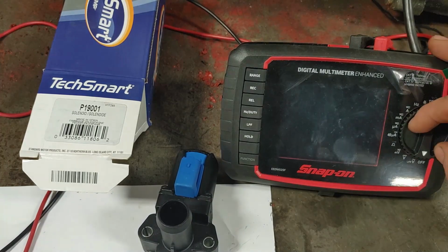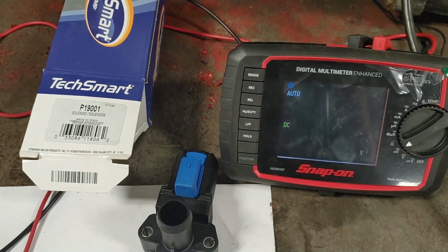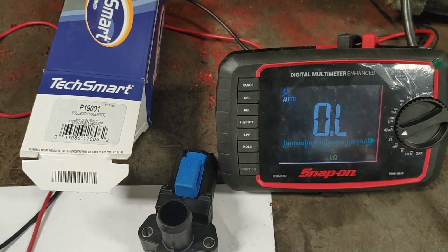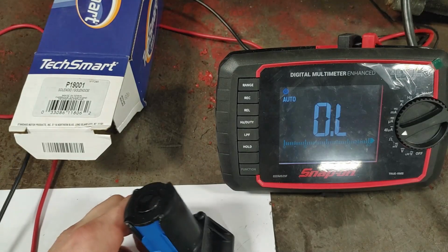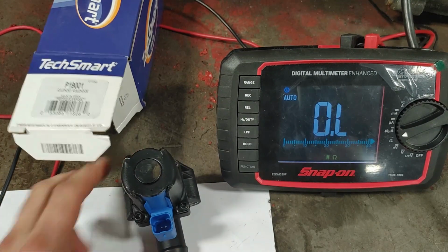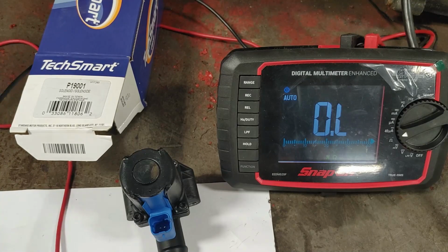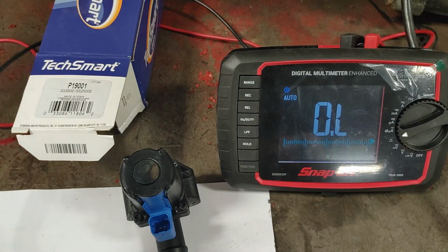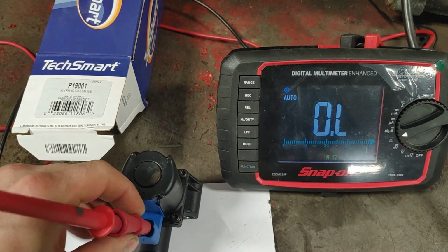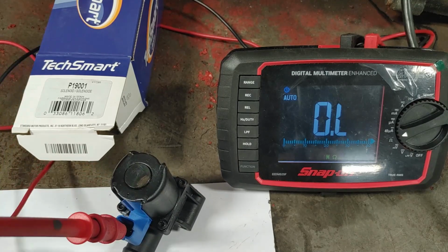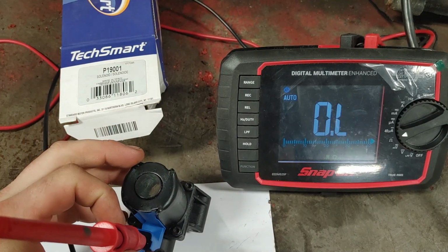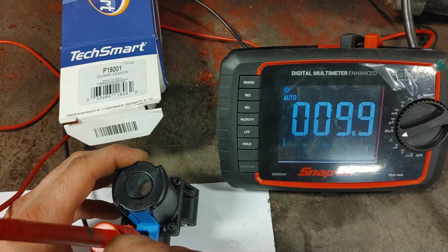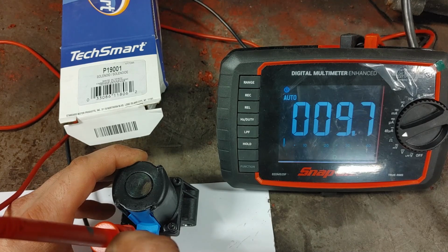So what we're going to do right here is that I just wanted to see what the resistance reading is on this one. If you remember correctly, the resistance of the old valve was 1.2 or 1.9 ohms. And I could not find a spec in AllData to give me the resistance value. So let's go ahead, hook this up, see what the resistance value is, so that way you guys know that if you're testing it and you see anything other than roughly about what the resistance value is on this one, then you more than likely have an issue with your valve. And here we have 9.8 ohms.